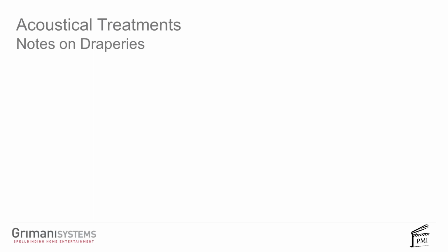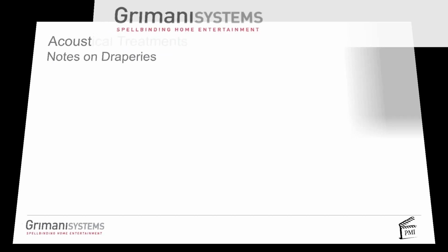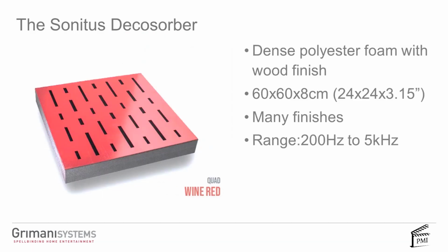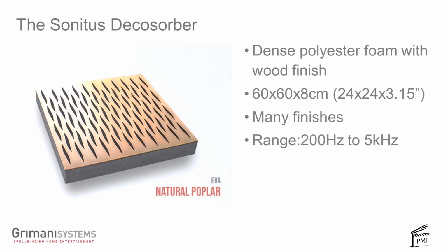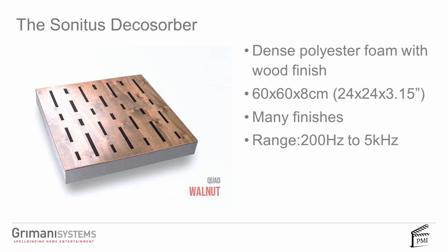Anthony, real quick on the Quad, for example, or any of them for that matter, would the size and shape of those decorative designs or openings change the acoustic characteristics of the panel if they were different? I'm just curious. Yeah, so this has a different high frequency reflection than this. This absorbs down lower, or reflects more high frequency energy, than that. So you have to be careful about where you use it. We tend to use this more towards the front wall of the room, where you don't want to absorb too much high frequency. You want to tame mainly the lows.